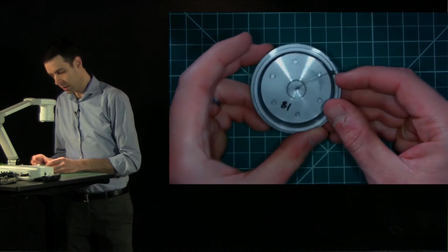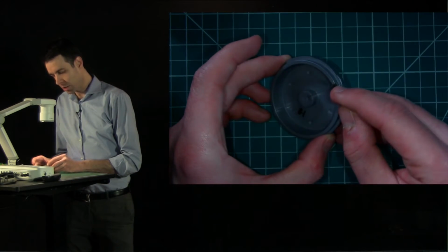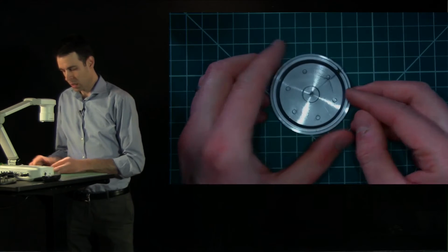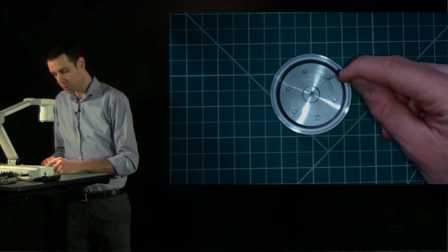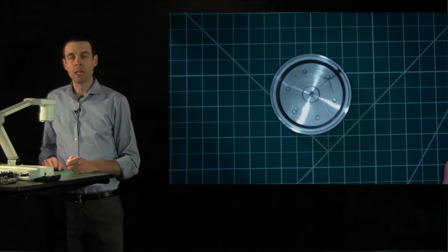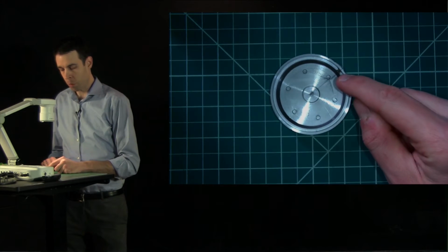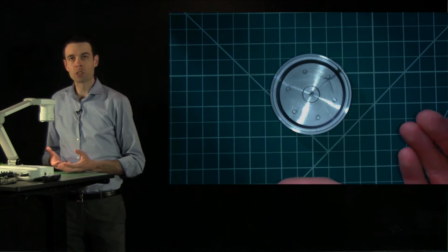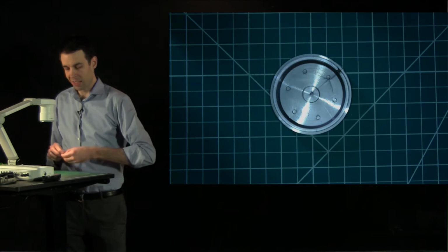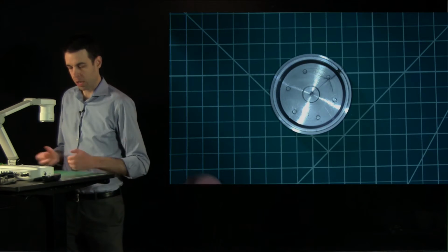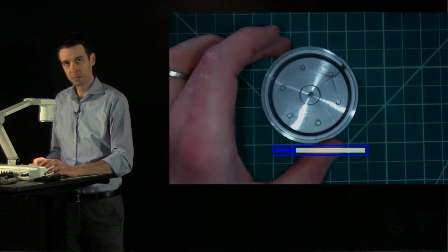And here on the camera is the same part. Here's the location of burning, and what the students did is they machined a small channel in their mold such that the air could escape and therefore burning didn't occur, but the channel was so small such that the plastic didn't flow out along that channel and create an instance of flash.